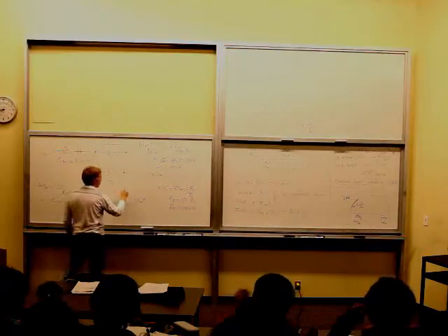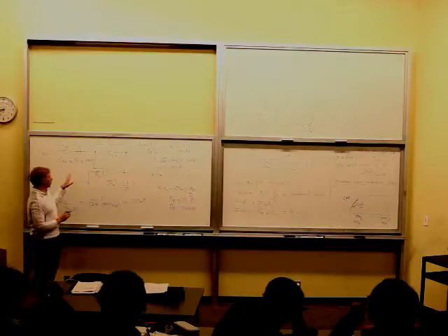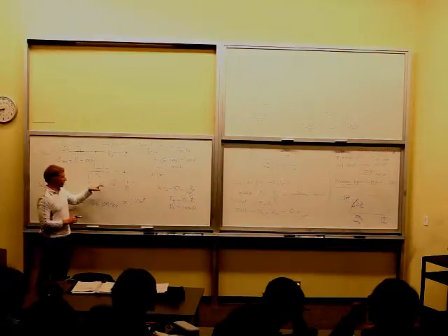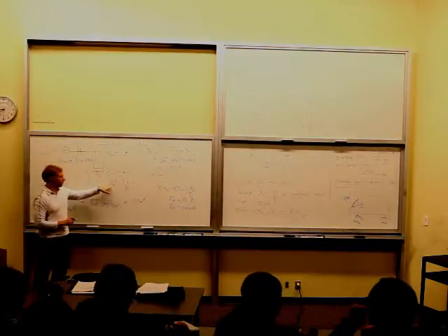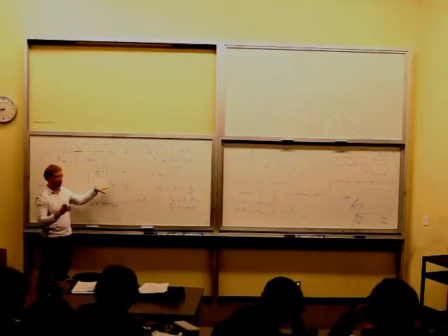You have to look at, well, what's the behavior of 1 over Zi? What's the behavior of 1 over Zf? And you'll find that one of them behaves like a high pass, one of them behaves like a low pass. So if you look at these impedances individually, you're going to find that one looks like a high pass times a low pass.